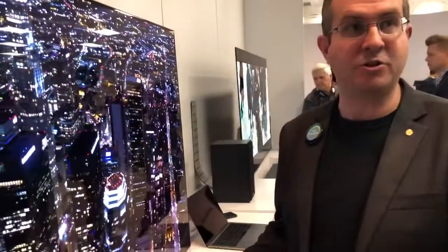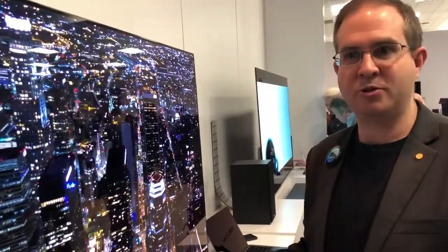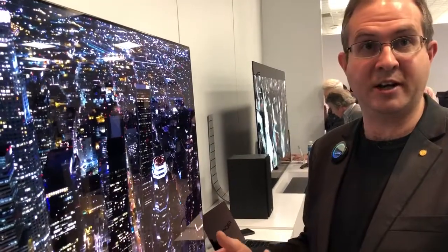That's right. The other thing, which I believe is exclusive to LG Electronics, is a feature we're not marketing because it's too complex, but I will tell it to you anyway. It's a different way of sending the RGB data to the panel that gives us pixel level control over the white boost. Some level of distortion happens because we're increasing white to increase the peak luminance, and we're able to adjust where that distortion occurs.